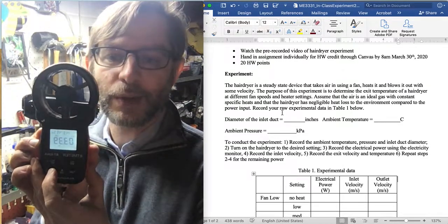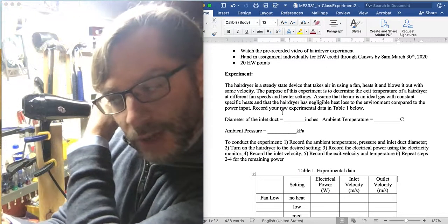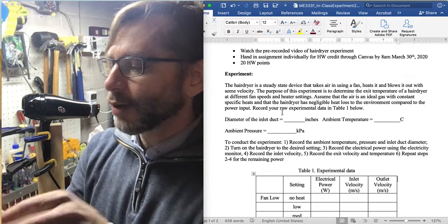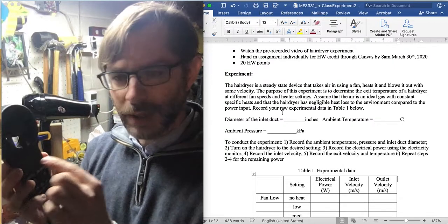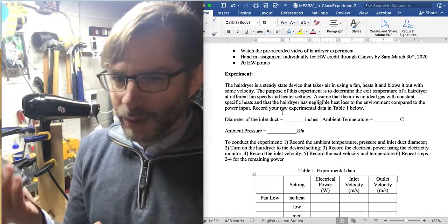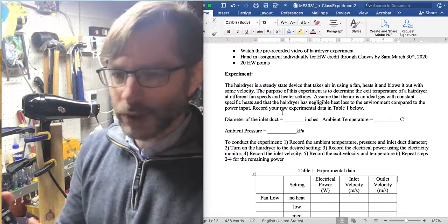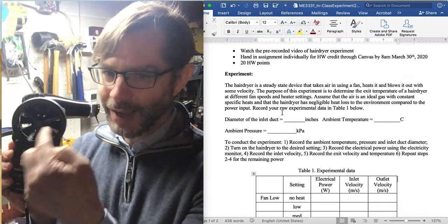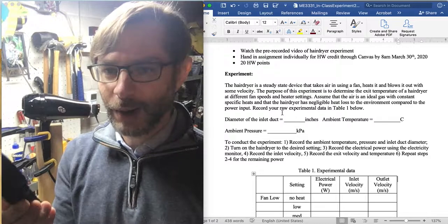You see the velocity increases in meters per second. Now notice that this anemometer also tells us the temperature of the air in the environment, as well as the relative humidity. We are not going to be using the temperature because it is measuring the room temperature in here, and the temperature takeoff is somewhere in the back. So it's actually not going to be taking the temperature of the gas coming through here. I learned that when I did the first dry run of this experiment.